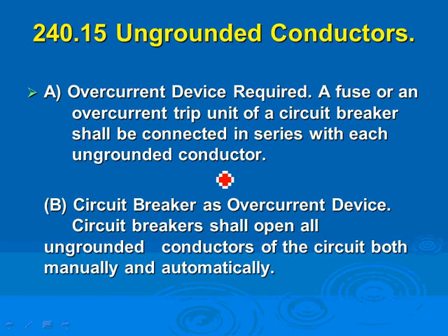And the ground fault protection, guys, looks at phase A, phase B, phase C, and neutral, and sees what's going out must come back equal. What's not equal is going to come back through ground. If there's a substantial difference, if it's a ground fault protection, it will trip. If it's a ground fault alarm, it will alarm. It has the capability of tripping or alarming.